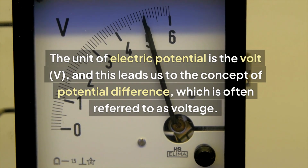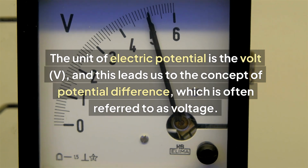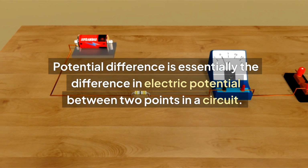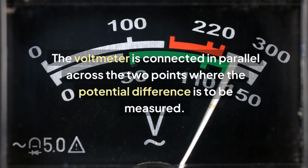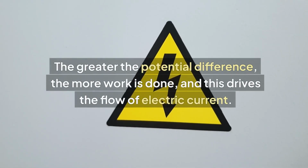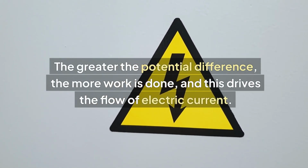And this leads us to the concept of potential difference, which is often referred to as voltage. Potential difference is essentially the difference in electric potential between 2 points in a circuit. It is the work done to move a unit charge from one point to another and is measured in volts using a device called a voltmeter. The voltmeter is connected in parallel across the 2 points where the potential difference is to be measured. The greater the potential difference, the more work is done, and this drives the flow of electric current.